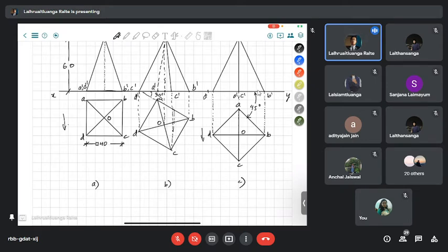All right. So here in my drafting, I did not align my top views properly because I wanted point C to be slightly lower, as in my conditions A and B are very close to the XY line. So to have a good, visually pleasing drafting, it is always better to have the tip part always at the same level.